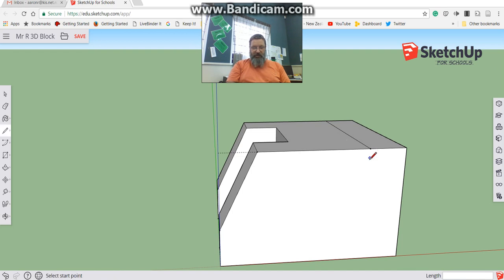Again, I'm using that center mouse button that's pushing down on the scroll wheel in order to be able to orbit around. Go back to my end point. This time I'm going to make sure the line is blue, and I'm just going to type 10. That will create a vertical line. You can see how this is already still attached. It's because this line didn't go to another line, it went to the middle of nowhere.